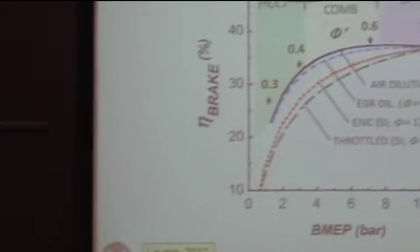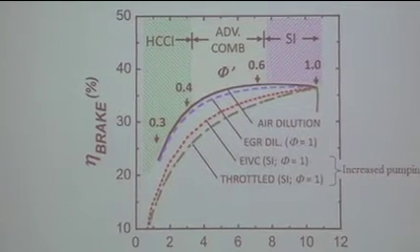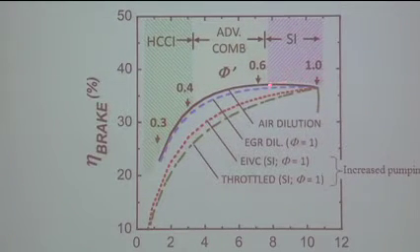However, HCCI is limited to relatively light loads, in this case around 3 to 4 bar IMEP. If you look at spark ignition engine combustion, though, typically this is operating stoichiometric or at equivalence ratios around 0.6 or 0.7, the lean limit for combustion. You can see that, again, there's a drop-off here associated with changes in gamma, which reduce the brake efficiency.